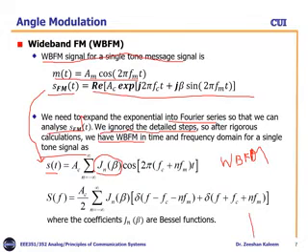For example, if you plot this one, this is your carrier and this is your sideband, right? So how do you know this amplitude? How much height will this sideband have? Previously we had the amplitude for that one. So in case of wideband FM, we will use Jn(beta) to calculate these amplitudes. These are the sidebands' amplitudes actually, right?